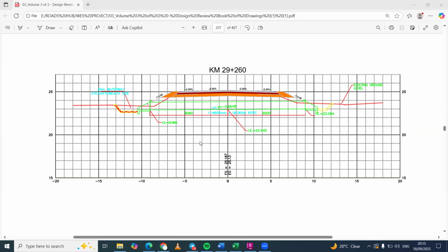So we can basically show the pavement layers like the subgrades and the subbase. We can also see their thicknesses. We can indicate the widths of our carriageway. We can illustrate where the ditches are, the flow lines, and all those elements that make up our road.